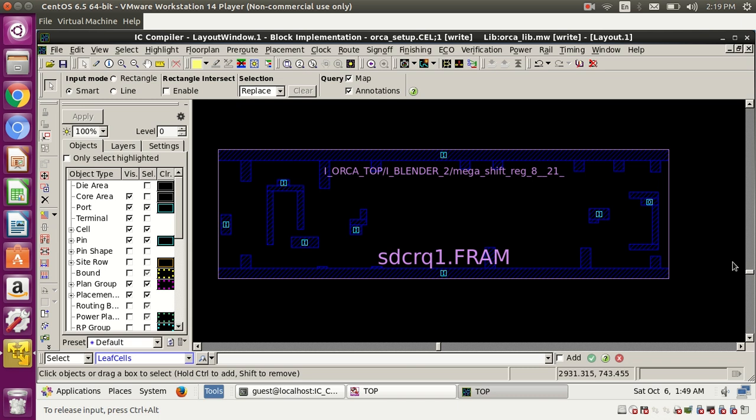We can check the clock reports. Suppose there are conditions where insertion delay is violating and skew is violating, but the timing path is met, then who cares? They are virtual things, not physical things. They are logical constraints we set so that it helps our physical things to be done correctly. So skew and insertion delay are not hard-coded limits. Until we meet our timing, that's it. Our timing is clean, so skew, insertion delay, whatever it is, we don't care about that.